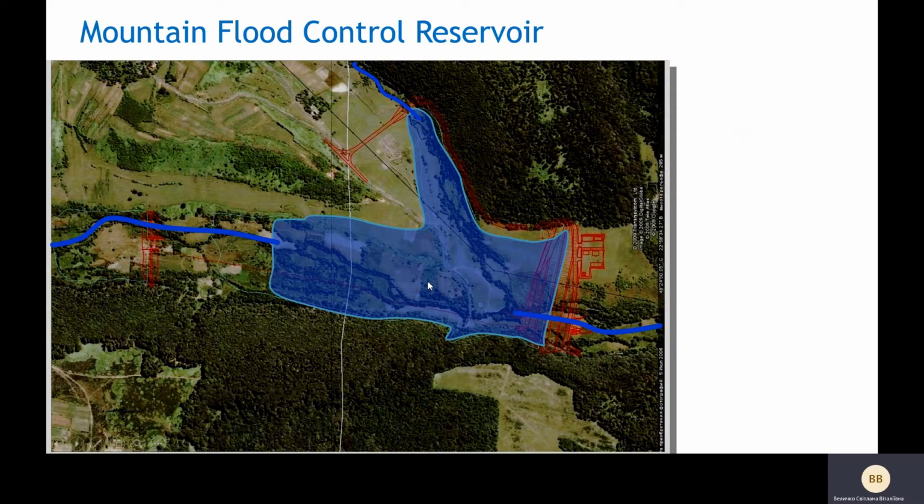The expected location of the mountain flood control reservoir is the Irshava River of the mountain part of the Tisa River basin. The dam is made of local materials such as gravel pebble soil with an impermeable layer. The mountain flood control reservoir leads to a temporary intensive water level rise and the same intensive fall of the water during the extreme flood.